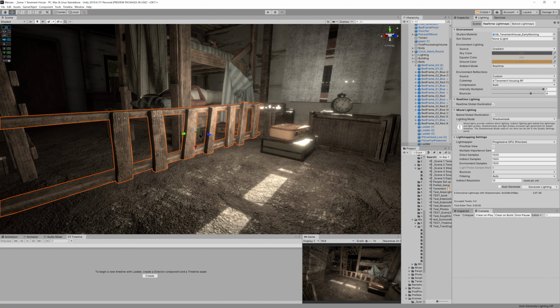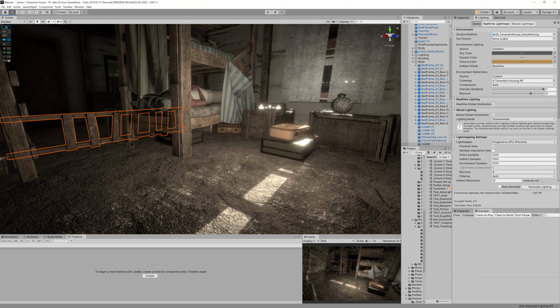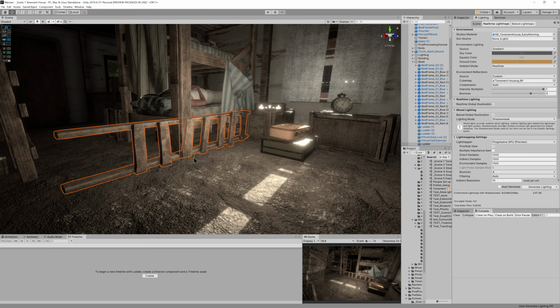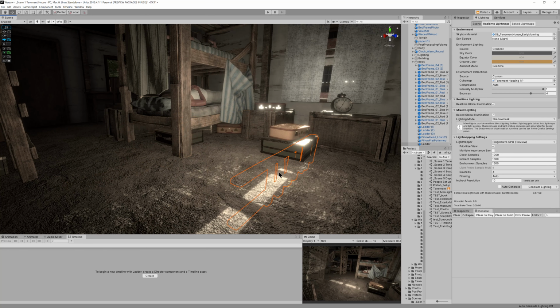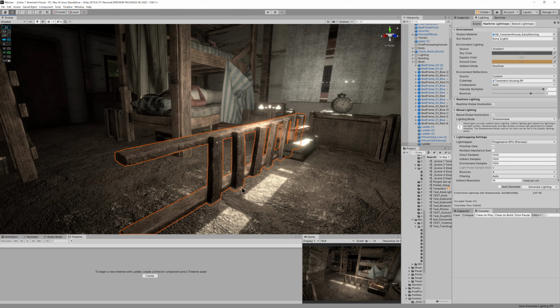Now, Unity does allow you to dynamically change, at least temporarily, the pivot point of the object using vertex snapping, using the V key, which we'll talk about more in the future. This allows you to move the object around based upon a selected vertex point and snap it to another vertex, which makes it easy if you know how to properly place vertices.